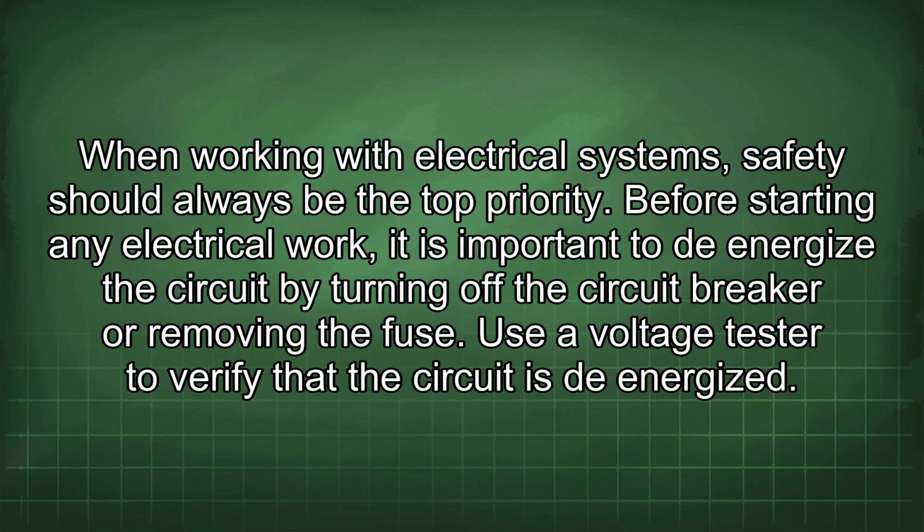When working with electrical systems, safety should always be the top priority. Before starting any electrical work, it is important to de-energize the circuit by turning off the circuit breaker or removing the fuse. Use a voltage tester to verify that the circuit is de-energized.